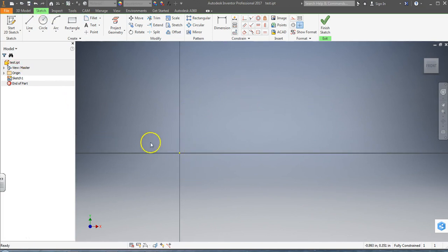And so I'm going to create something. One of the things that's really helpful is to always start one corner of something here. So I'm going to go really basic. Let's go line. I'm going to start at the corner. Now, if you look at this, I have degrees and I have a distance. So if I'm going on an angle, I can type in this distance. Let's say I'm going to go 5 inches.